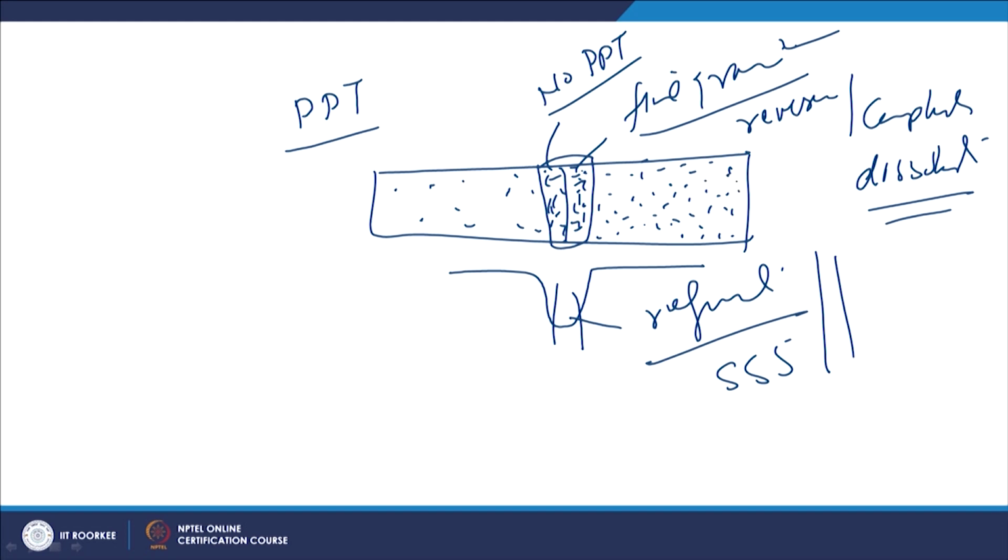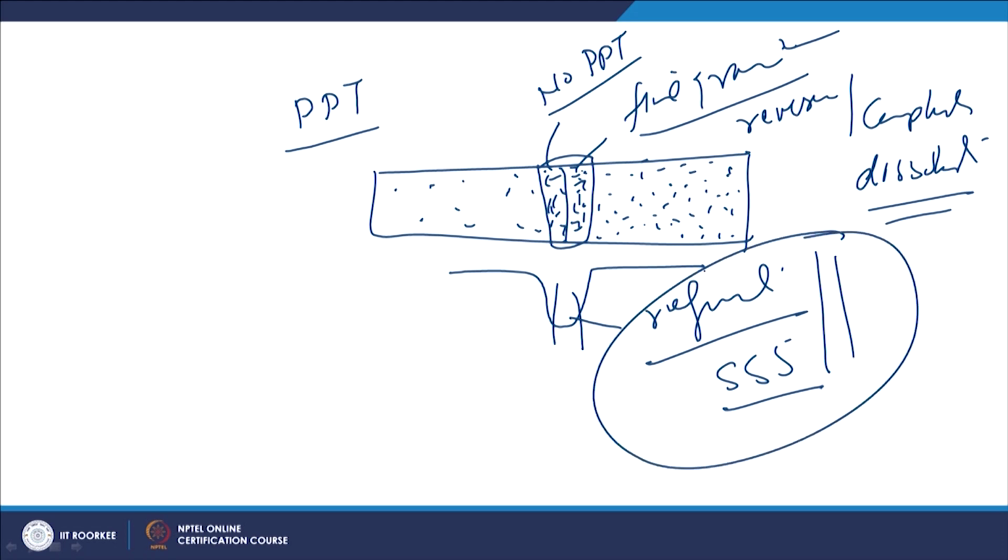So, although dissolution will lead to solid solution strengthening, and the fracturing and refinement of the particles will lead to grain refinement, despite the combination of these two strengthening mechanisms, the major factor contributing to this kind of metal system was the formation of the precipitates. If these precipitates are lost, then we will lose the hardness and the strength of the joint. So, this is the case where solid solution strengthening and refinement are not working at all. It was the formation of the precipitates that was primarily responsible for the strength of such a metal system.